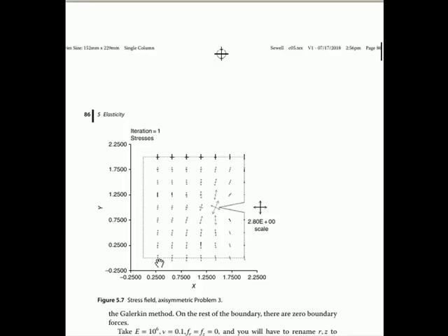If you have a problem like problem 3, an axisymmetric problem, basically your region is like this: r equals 0 is the z-axis here. If you rotate this around the axis, you get basically a cylinder with a notch all the way around. So just imagine rotating this all around. Then nothing's going to depend on theta, so you can solve the problem as a two-dimensional problem, and that's what's done here.